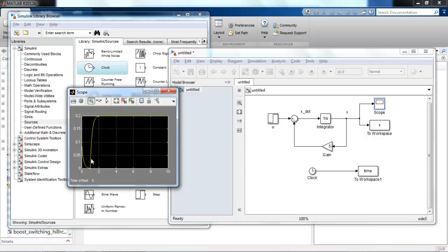You can see that it has the shape that it had before, except here you can see the initial condition on X was 0.1. So without any forcing function, the solution is going to just be exponential decay, e to the minus 5t. And so that's what happens. Initially it just decays. This is the free response, or this would be the homogeneous solution if there was no forcing input. And then when the step occurs, we get the same sort of shape that we saw previously.